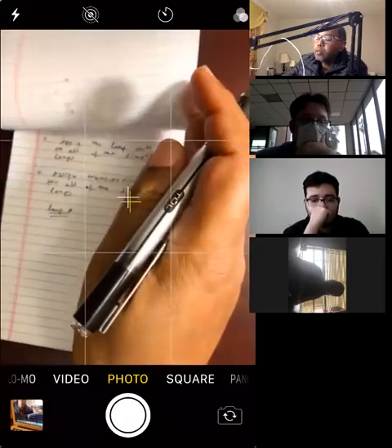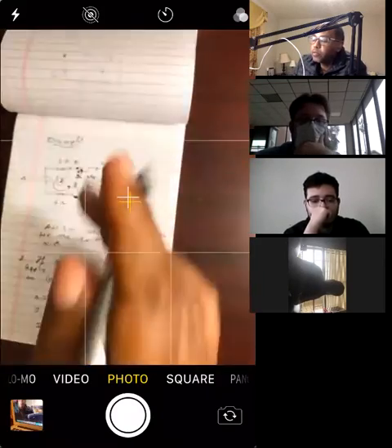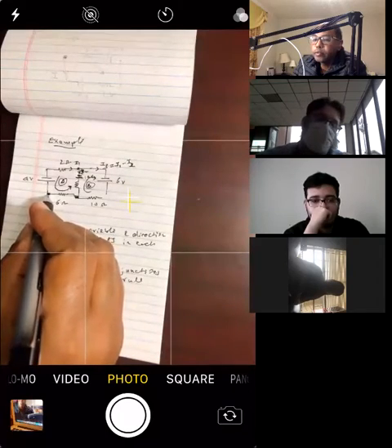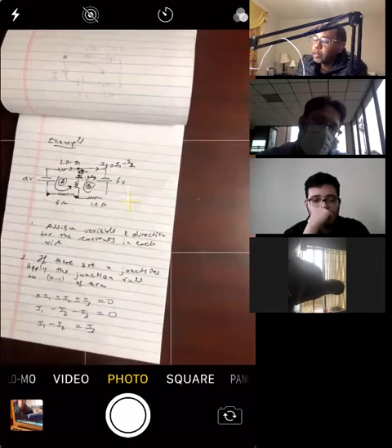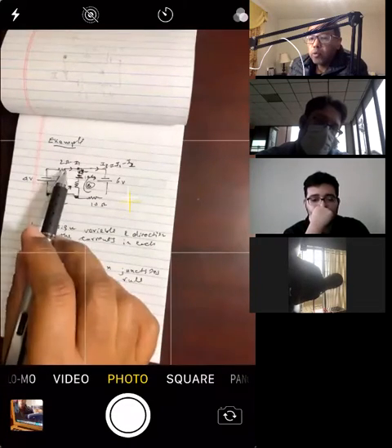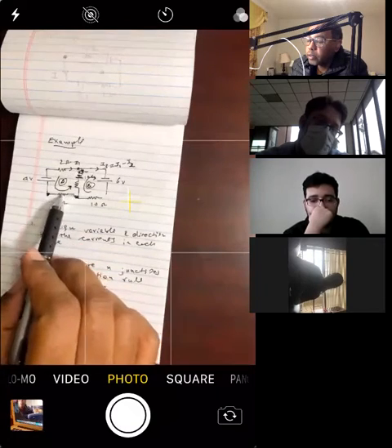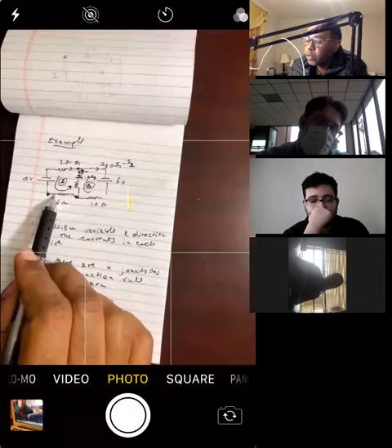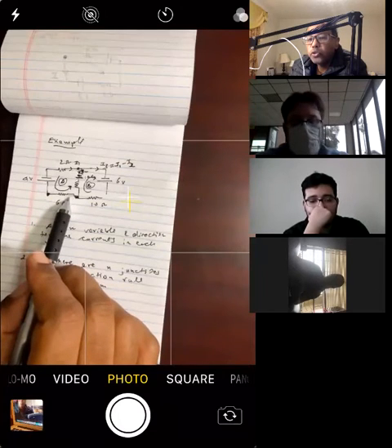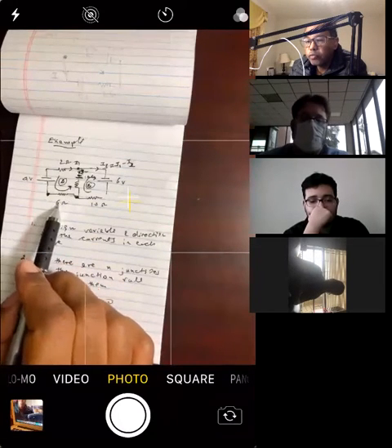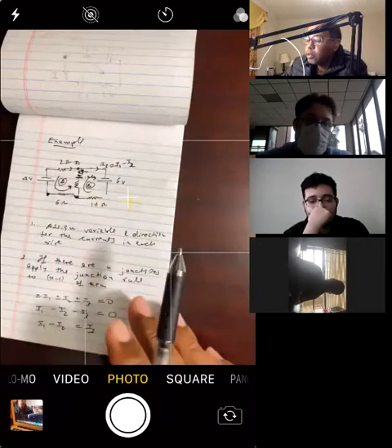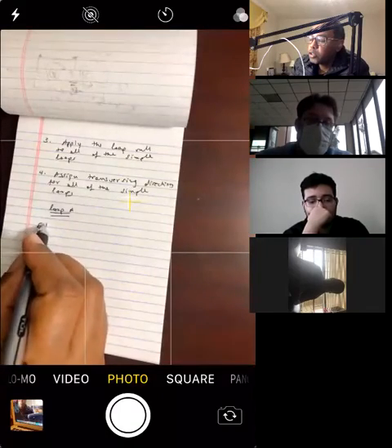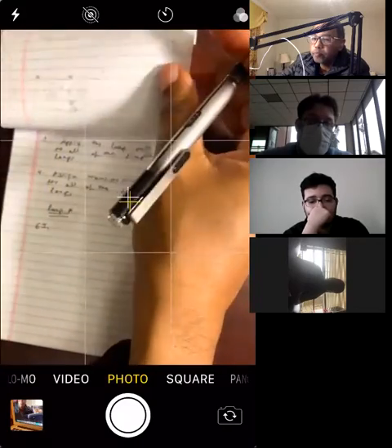Now it doesn't matter where you start, but you have to decide where you want to start. So let me start over here. I have to go all the way around and come back over here to equate to 0. I1 is going this way, right? So when I cross this resistor, I'm going opposite to the direction of the current. So this potential difference should be positive, and the current is I1. So my first potential difference is, from Ohm's law, 6 times I1, and it's positive.